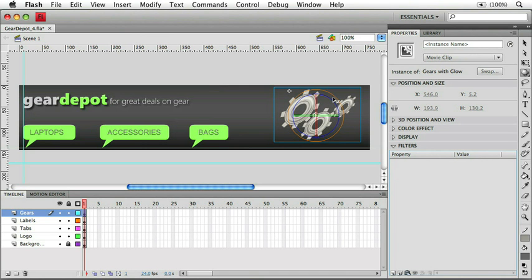If you move your cursor over the blue handle, which appears as an outer blue circle around the other 2 handles, you'll see it produces a small Z below the pointer. This is our Z-axis and allows us to rotate it almost as if we're on the face of a clock, going either clockwise or counterclockwise. Click and drag on that handle and move in either a clockwise or counterclockwise fashion, and you'll see it rotates the graphics as they exist now around that Z-axis. You can almost think of that Z-axis as a bar that runs from the tip of your nose to a point directly in front of your face, going straight ahead.